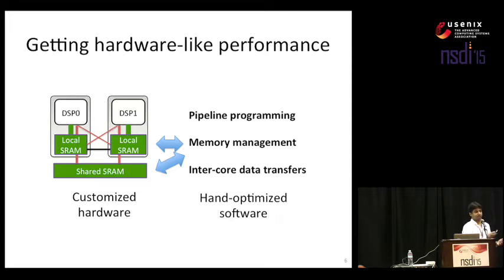Another feature that these platforms typically expose is, instead of providing rich cache coherency across multiple cores, they make available low-level interfaces to carefully orchestrate data movement between different memory regions. Now, why that matters for these kinds of applications is because the programmer can very carefully tune when data is moved between memories and therefore control the effects on timing and achieve the latency requirements of the protocol.